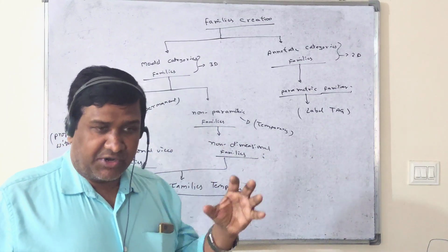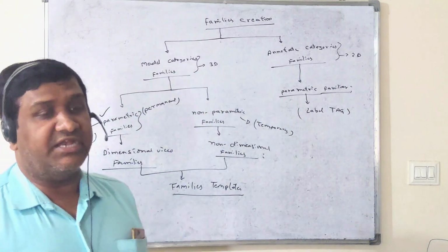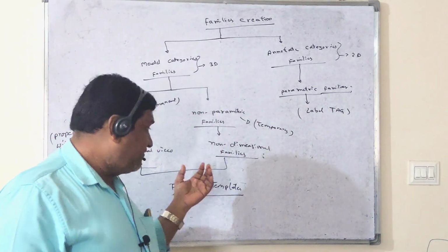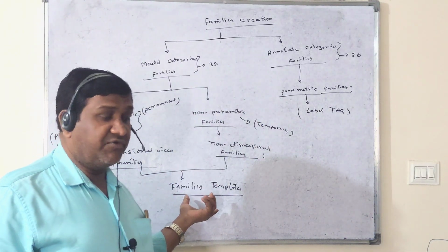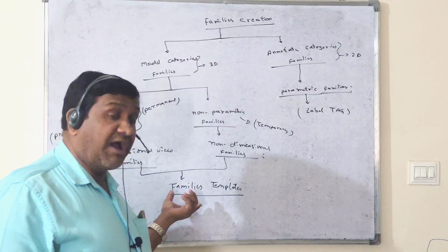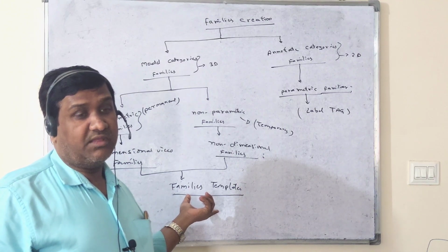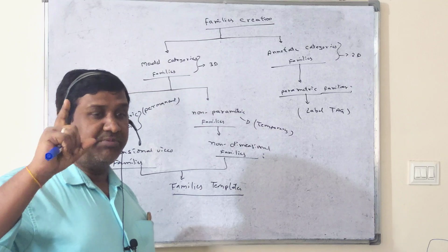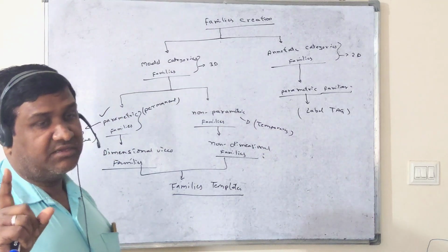How do we create a project? With the help of a template only. So here the families also we have to create with the help of family templates only, because each template creates one family.